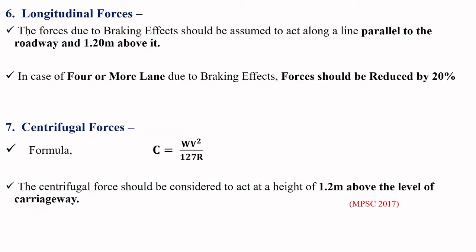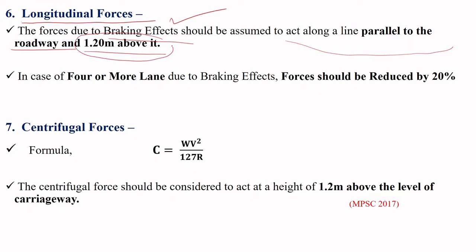Now the sixth provision, that is the longitudinal force. For the longitudinal force, the forces due to braking effects should be assumed to act along the line which is parallel to the roadway and 1.2 meter above it. Very important MCQ. They will directly ask the value.